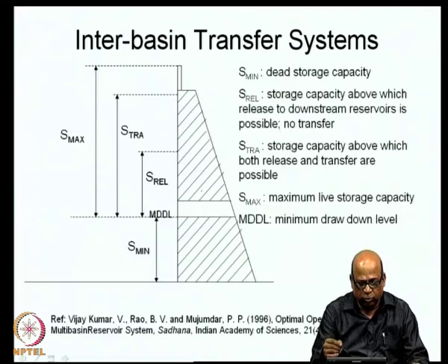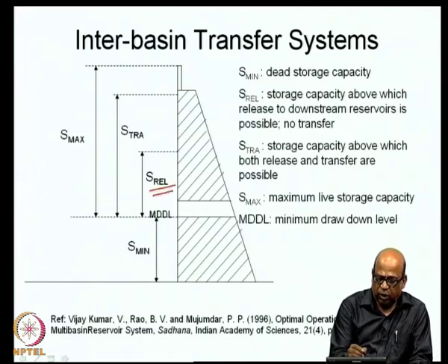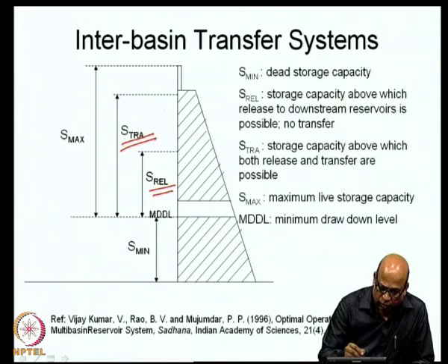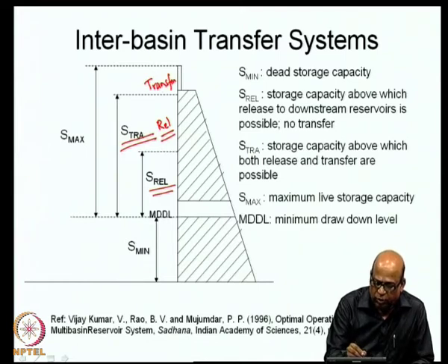Alright, there is one more small issue here. We said this SREL and STRA are the storage zones. They determine the storage zones within which release and transfer is possible. So, in this zone release is possible. By release I mean the amount of water released for downstream requirement, that is the requirement of the downstream reservoir, and this is the transfer zone. If you are above STRA, you make the transfer.